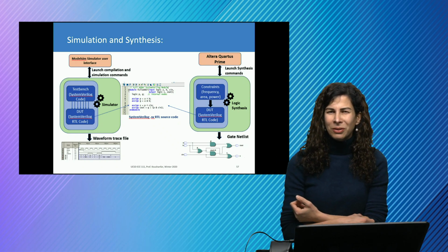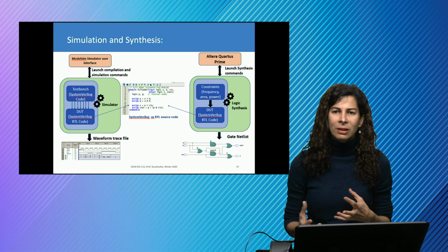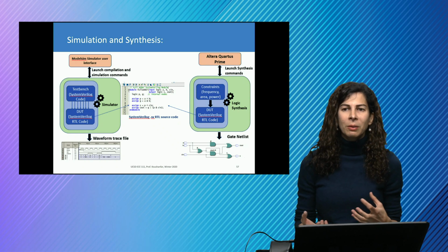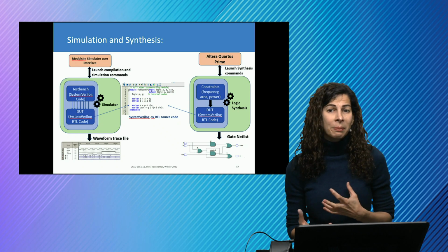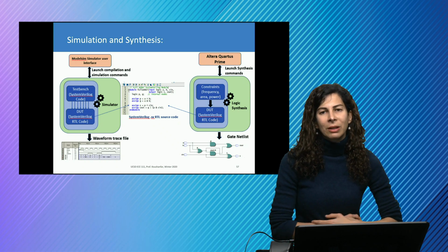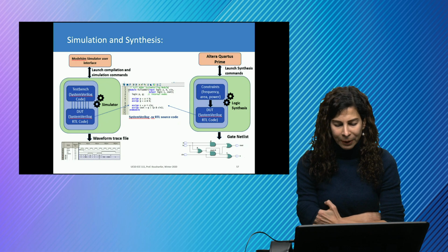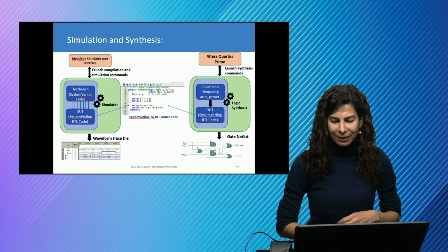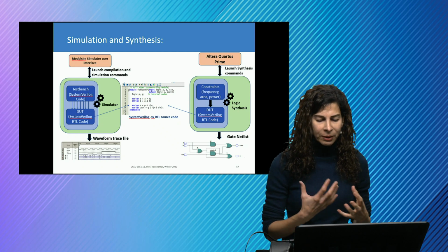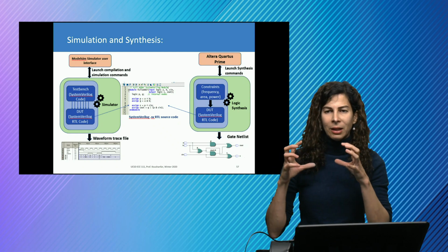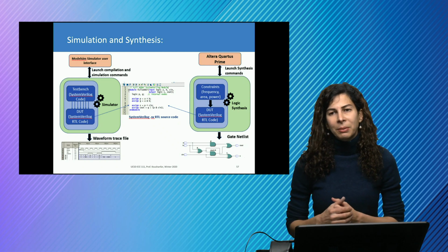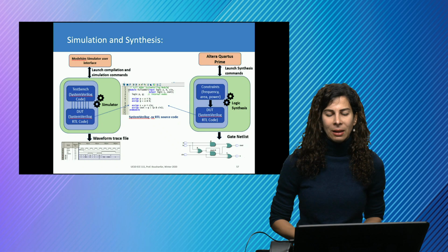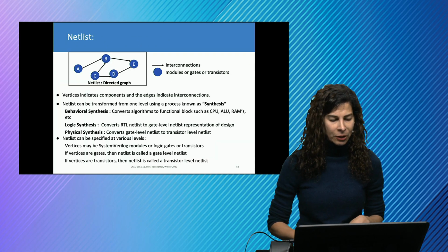What happens in typical design is that we give part of these design criteria as constraints, and then we try to optimize only one of them or a combination, for example, area delay product, but giving one of them as a constraint. And the design under test is, again, part of it. We define a real construct, such as a built-in self-test, that we use in testing of the chips to test this piece of design in logic.